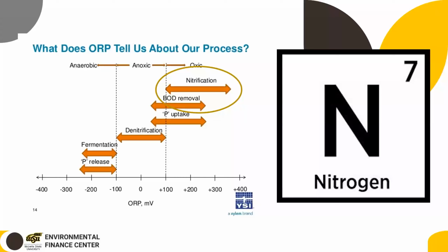And then when Nick was talking about the chemical addition, for plants that are going to use it to polish or on bad days, I think you would want to add that chemical after the aeration, right? Because if you add it before the aeration, that's going to minimize the biological portion. Yes. Unless there's an SBR, you couldn't really do that.